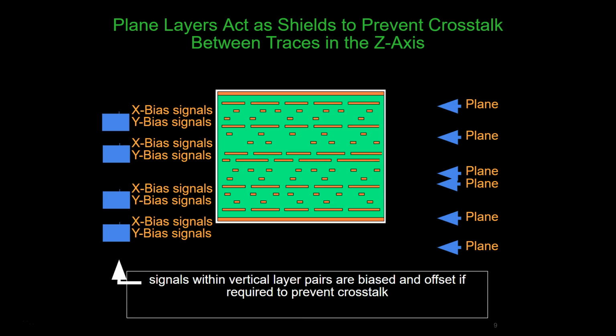Now here it shows the vertical cut of a 16 layer PCB. If you count this, it is a 16 layer PCB. This is not the best view, but it does show how to maximize signal layers and keep enough ground plane layers available.